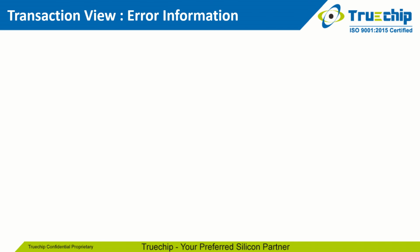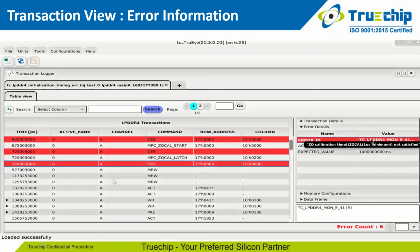Then comes the transaction view with error information. Say we have run a test and there comes a UVM error. When we have to see at what time and what error has occurred, this representation will show each and every piece of information regarding that error, with its expected and actual values, meaning what was the expected value as per the spec and what value has been received by the monitor, at what time scale and at what command, with multiple more fields as per the error, which plays a vital role in debugging easily.